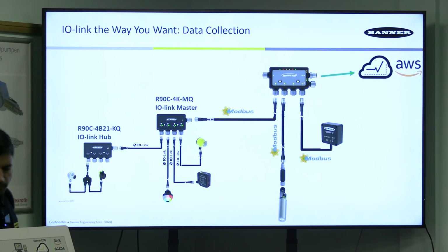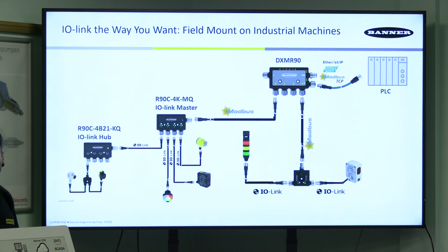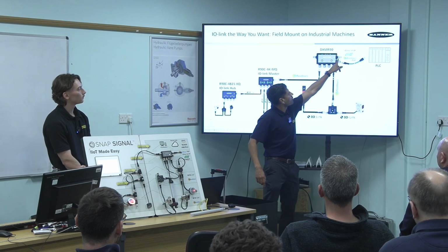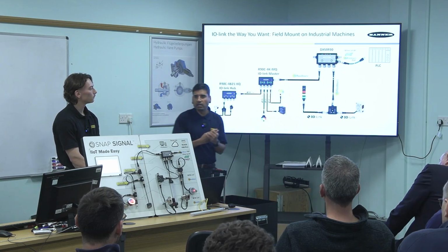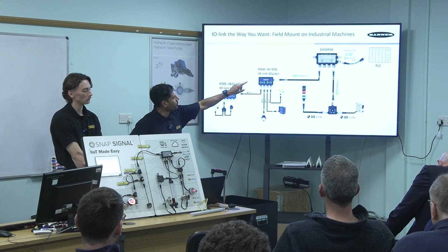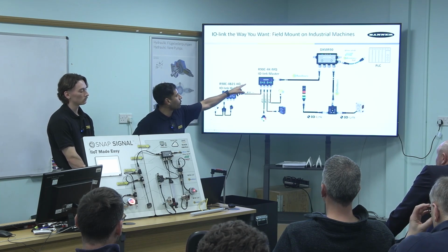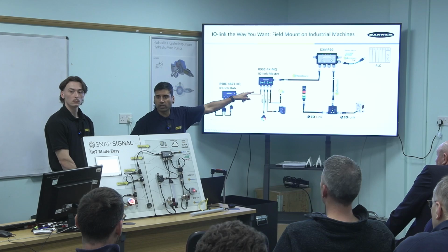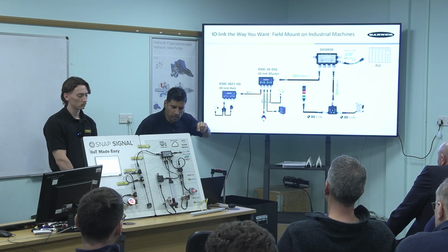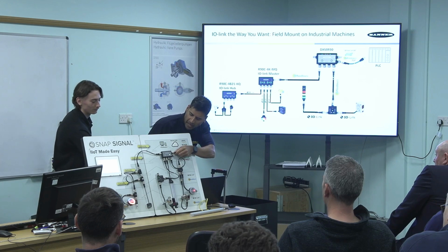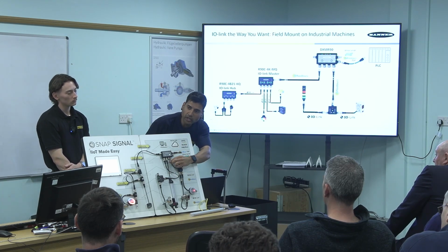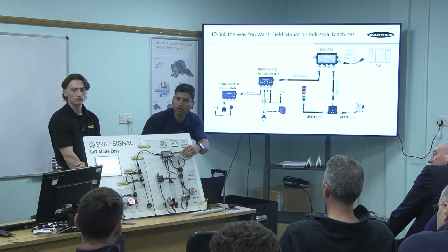Excuse me, where is the power coming from? From this port here, that's a power port. Pins 1 and 3 are your power, pins 4 and 2 your signals on Modbus. Because it runs parallel, you get power out of these ports on 1 and 3. 24-volt supply. Into it, yeah, that's right. Like here, that's just got power. So there's power in there, and then from each of these, you get power. So the master will distribute power.